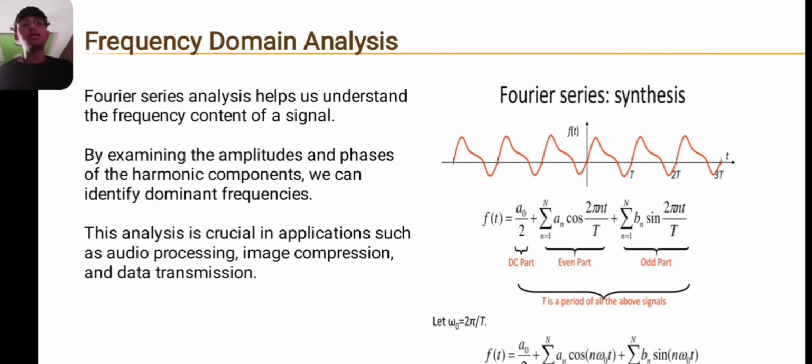Next, third one, frequency domain analysis. Fourier series analysis helps us understand the frequency content of a signal. By examining the amplitude and the phase of the harmonic components, we can identify dominant frequencies. This analysis is crucial in applications such as audio processing, image compression, and data transmission.